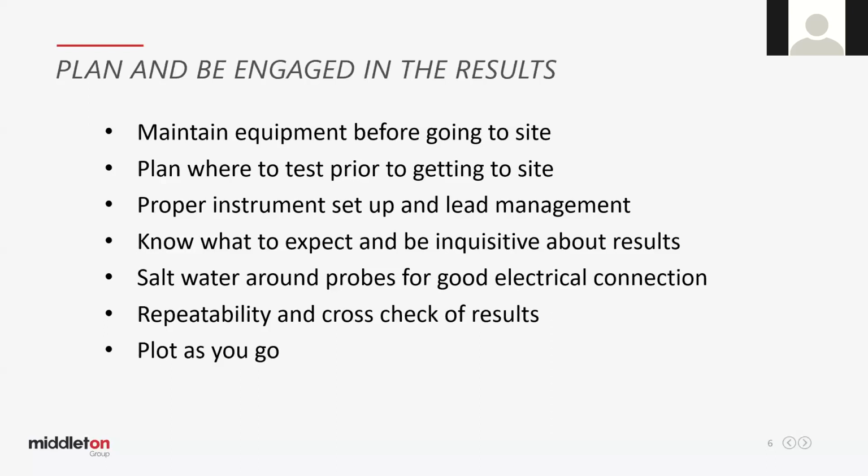Take plenty of water with you. Salt water is even best. Just some salt from Coles or somewhere and put it in the water you take along to make salt water. And put plenty of it around your probes for good electrical connection to the soil. That's a winner every time, that one. I try to do it every time, even if it's moist, still put some salt water around your pegs for good contact.